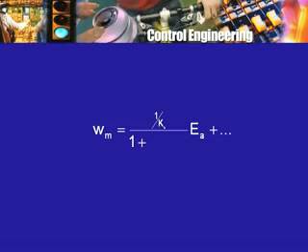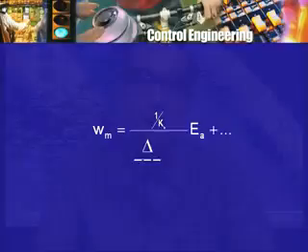So for our problem, fortunately, the calculation is very simple. I simply have 1 minus loop gain, and therefore I have 1 plus kf Ra divided by kt into kb. That is going to be the denominator of the multiplier for Ea, and this denominator, because it is really related to a determinant, is sometimes called delta for the signal flow graph. In fact, this same delta will appear in all the terms.